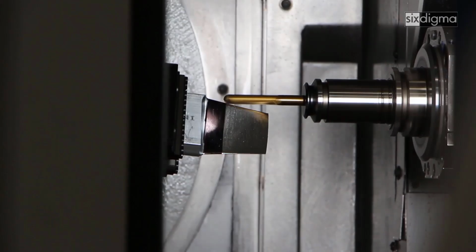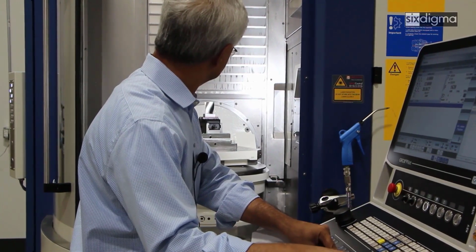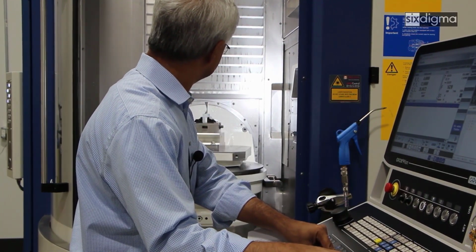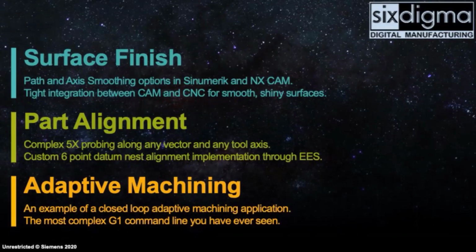As you can see, being able to exactly locate the part has many applications. Airfoil repair, being able to correct coatings, being able to machine the datum surfaces of ECM'd, cast, or forged parts. This is also very useful in centering 3D printed parts inside the intended volume and machining datum surfaces.